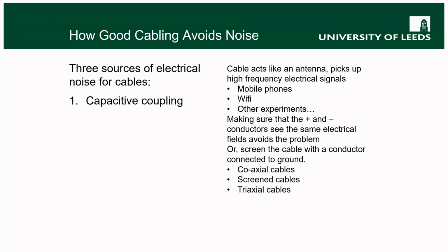In the triax cable, it's the outermost conductor that's screening the inner two conductors. In coaxial cables, you might have simply the outer of the cable being the ground, the screening, and then the inner is your signal lines. Whereas something like a banana plug is hopeless in this because there's no screening possible.